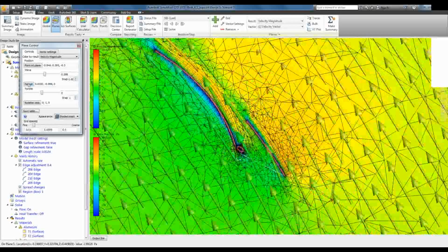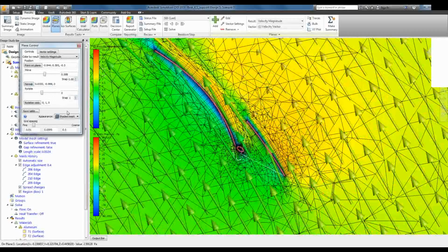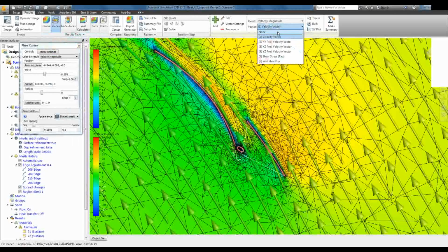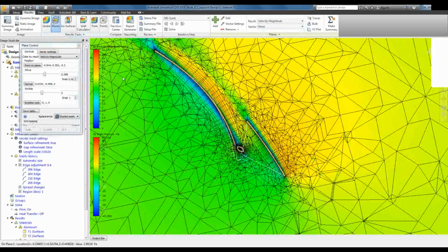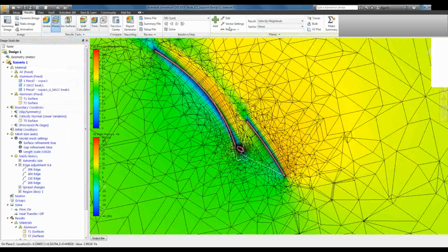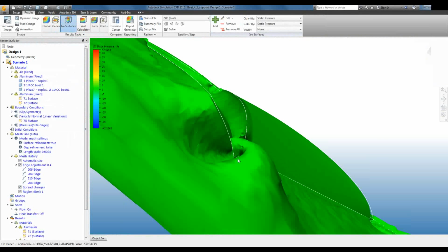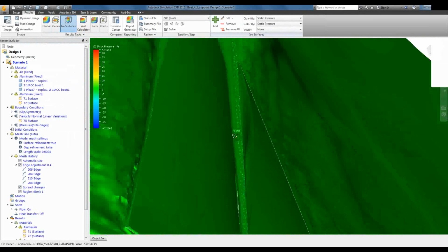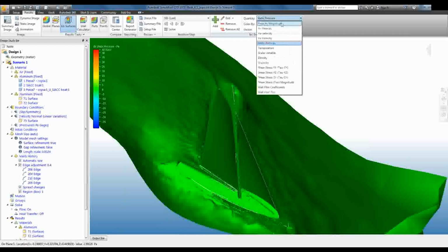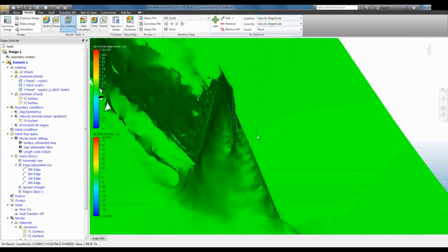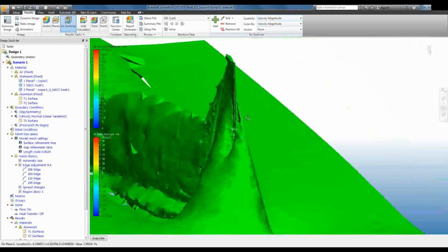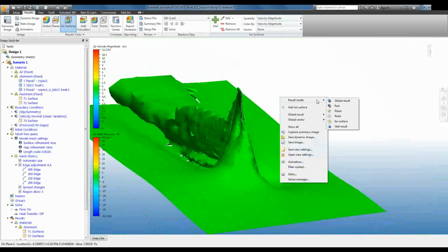Okay. Hey, Peggy, I had a question. Oh, sorry, you carry on. No, go for it. I was just going to mention what we were just discussing about the ISO surfaces, whether it's possible to show a very low velocity ISO surface with some vectors on it also. Ah, okay. You're taxing my abilities here. Okay, let's get back to it. So you just open that up, switch to velocity, and just switch it to like a 0.01 sort of value for the ISO surface.